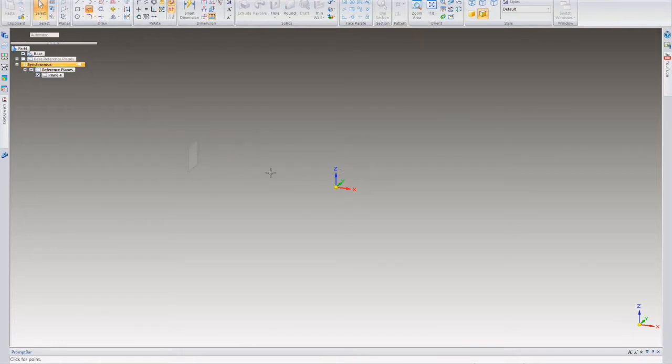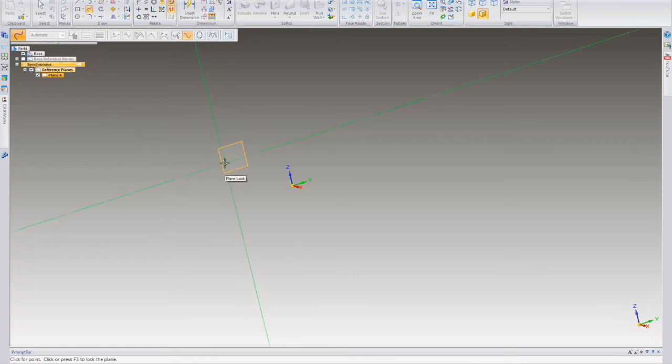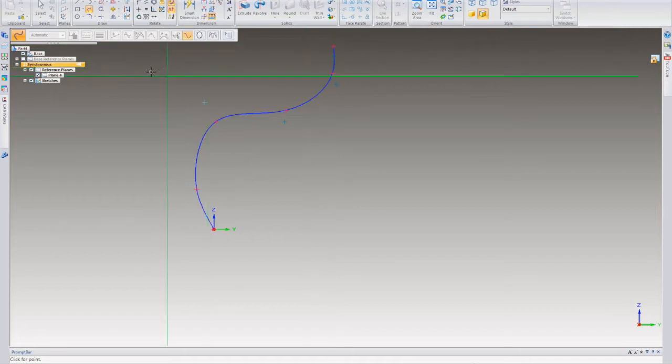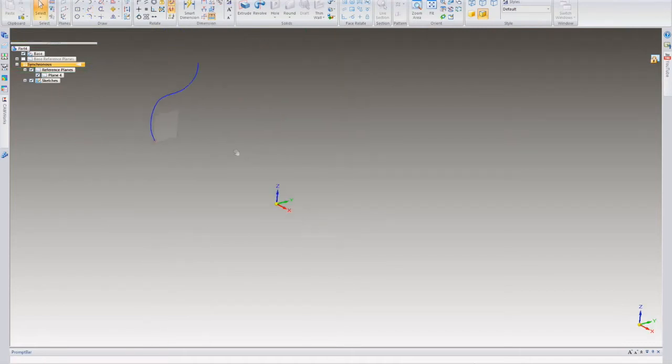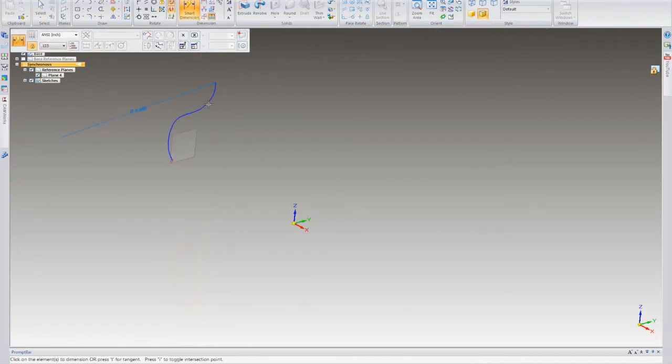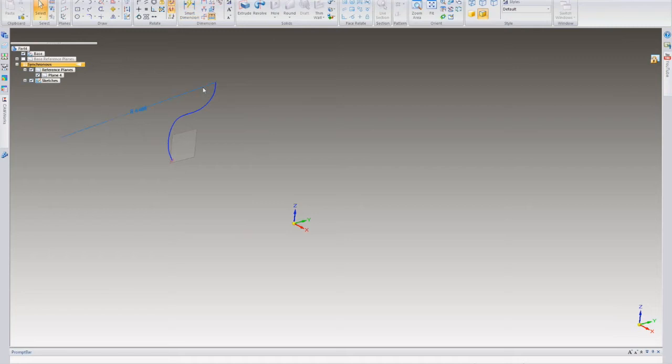And of course, I'm going to go ahead and create a sketch on this reference plane off in space. I'm actually going to create a curve in this situation. So I'm just going to use the reference plane here and just create some little simple shape. There we go. All right, so that's really all I can do with the synchronous. Of course, I could always throw some dimensions on here if I really want to start positioning this, but usually with surfaces and curves like that, you kind of want to let them free flow just for the meantime, just to kind of get the shape you want. Then you can go in there and do the final design. You change the dimensions to match what you exactly need.